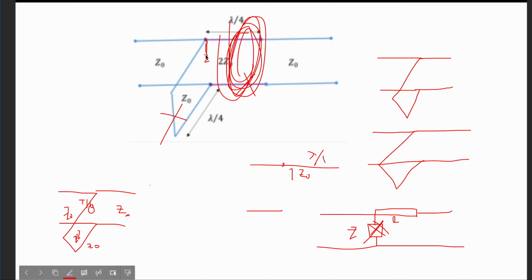But I am saying if it was not infinite, then you have some shunt part also here, then the effective circuit will get modified. And for that we need to see how to calculate the ABCD matrix if you have both parallel as well as series connection. One way to do that is to use the cascade network theorem, which says you can just multiply the ABCD matrices of both of these networks individually and you will get the final ABCD matrix. That will not come, but I told you for your understanding. This is clear, right? I can go.